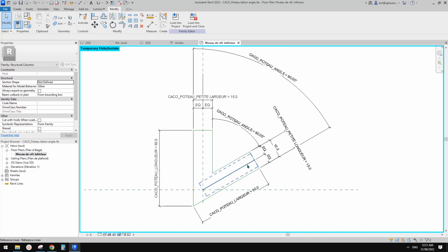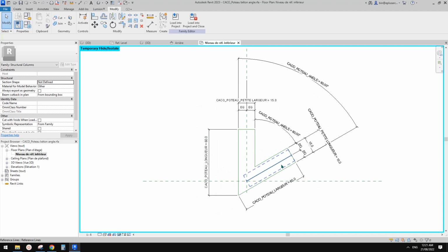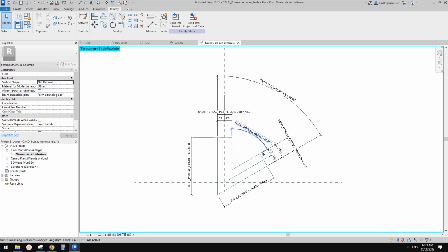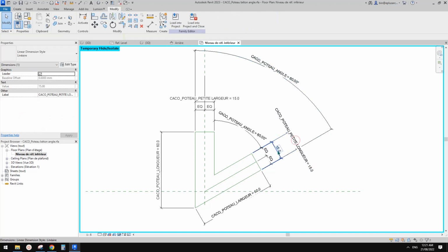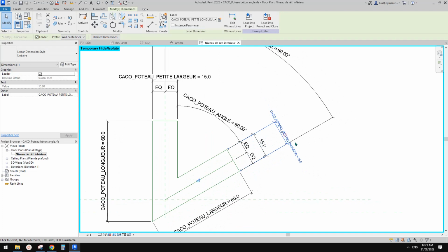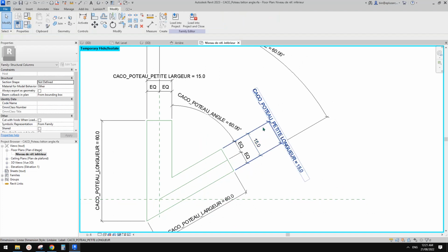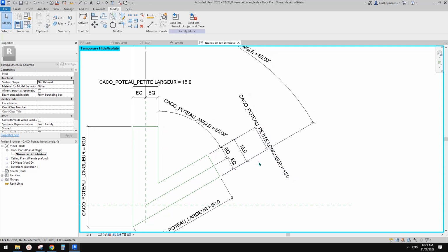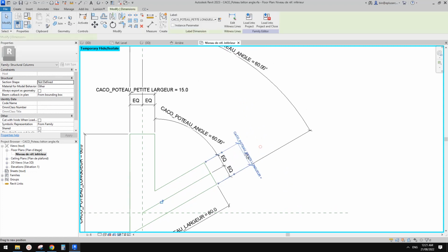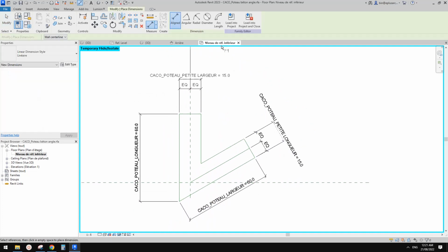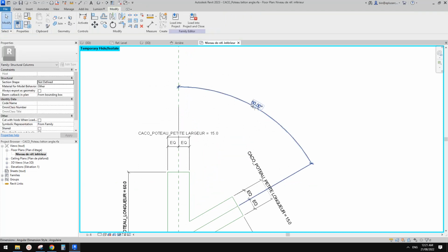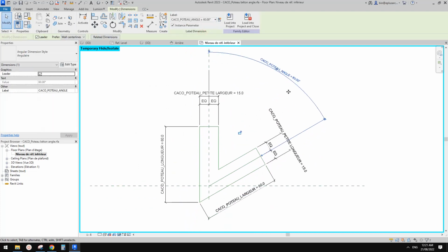So they will follow the angle of this reference line, so we no longer need the other two. And the equal will be all fine. Yep, all good. And what's this one? Why is there a 15 here and another 15? So let me try to delete some of these. Delete this 15 because that's over constraint. I'll delete this one and this one and add an angular dimension from here to this reference plane, and I'll just apply that 16 degrees to it.